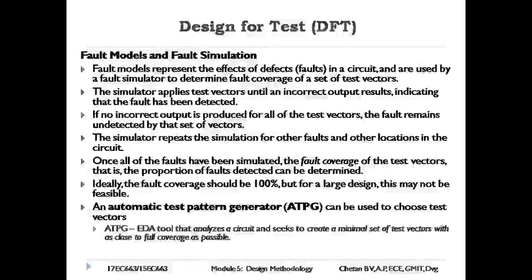Design for test (DFT). Design for test enhances testability of a product, thus reducing test cost. Testing involves applying test patterns to a circuit's inputs and verifying that the expected outputs are produced. The intention is to verify that the manufactured chip performs as designed. Additional circuitry is included to improve the system's testability. Such circuitry includes elements that make internal nodes observable or that perform testing automatically as a special mode of system operation.